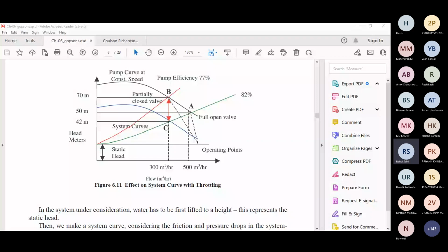This is another case. If I have a controller in the discharge of the pump, the valve opening will be decided by the control loop that I have provided over there. So for the case, let us consider that it is provided with the LCV loop. Control valve is provided with the level control. So the valve will continuously fluctuate as per the level. Correct. So in that case, you should give a recirculation line.